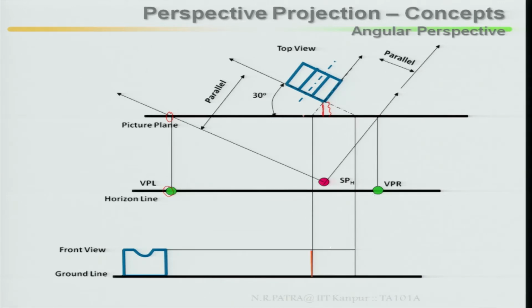So, actually this is the face, this is the surface you are getting, considering as if it is touching your picture plane. Once you get this line, this is the view of the edge of this side. I extend this particular one to the right side and project it back. This will coincide with your right vanishing point, so I draw it to your right vanishing point.